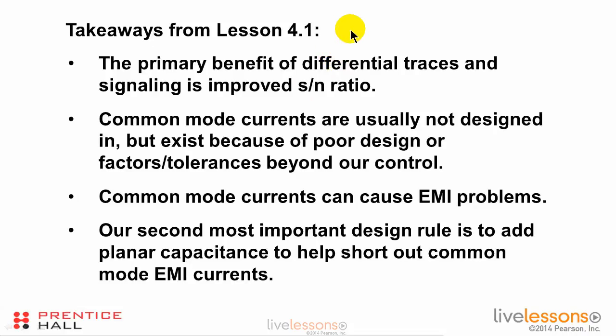The takeaways from lesson 4.1. The primary benefit of differential traces and signaling is improved signal-to-noise ratio. There's also improved timing, but that's typically not a terribly important benefit. Common mode currents are usually not designed in, but they exist because of poor design or factors and tolerances beyond our control.